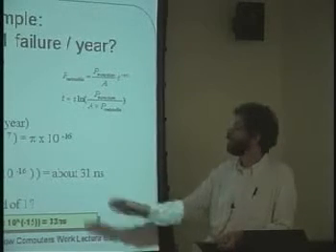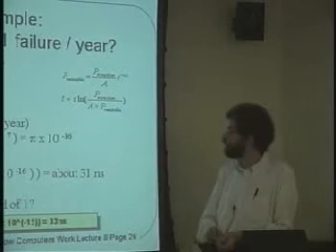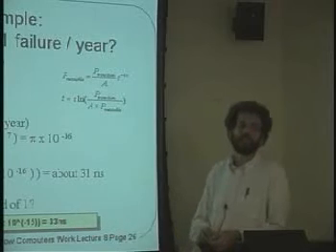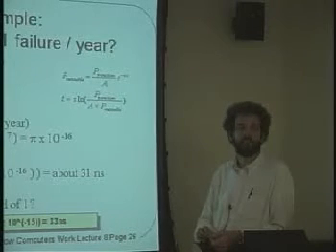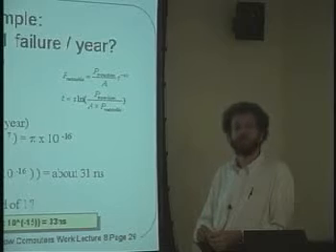And so if we want to decrease the probability by a factor of 10, it turns out we only need to wait 33 nanoseconds instead of 31. How fixed is the value of tau? Because that has a tremendous effect on the system.